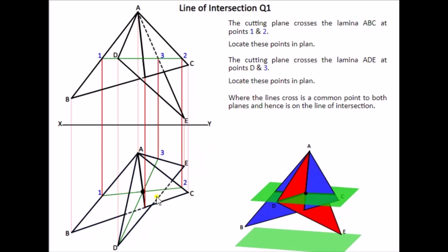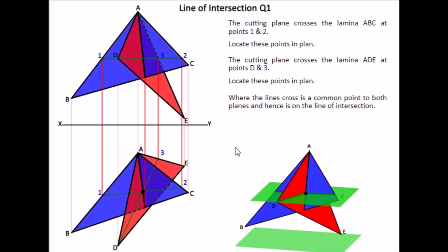And then in the plan view here, again, E is down near the ground, the height of it. C is up in the air here, so that means C is going to be higher, so this is a dotted line in this location here. So introducing the color, then we can see how the 2 triangles intersect with one another, and we have the line of intersection found. Obviously the next section on from this would be to find the dihedral angle for these 2.